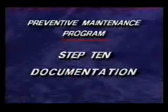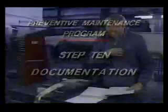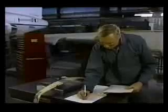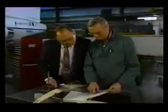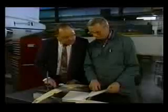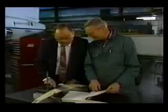Step 10 may be a mundane paperwork-filled task, but it is very important when it comes to keeping your aircraft corrosion-free. You must keep accurate records of corrosion inspections, repairs, and any deficiencies you discover. Take photos to attach to reports. You must also report any material or design deficiencies to the aircraft manufacturer and notify the FAA so that corrective action may be taken if required.